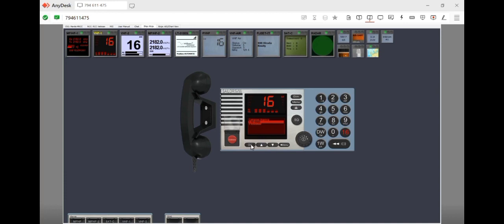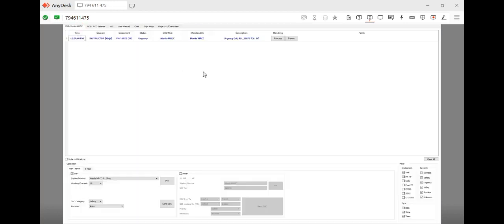At this time, choose all ship, press OK. Radio telephony, ship, aircraft, medical transport, just choose whatever you want. At this time, choose 1, press OK, then enter working channel. At this time, choose 16, just for example, then press OK and OK again, and it will be automatically transmitted. There you go.